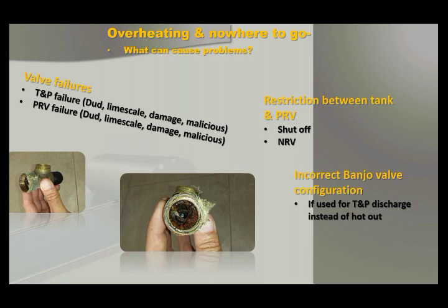Those plungers are not always well positioned in the spindle, and they can sometimes drop off. So that plunger, if it's installed vertically, it can drop and sit against the seat, and you have pressure coming from the geyser side trying to move backwards through that stop tap. It's actually pressing that plunger down onto the seat even harder. And that in itself, without any input from a human side, can then act as a non-return valve. And so shutoff valves can really cause problems.